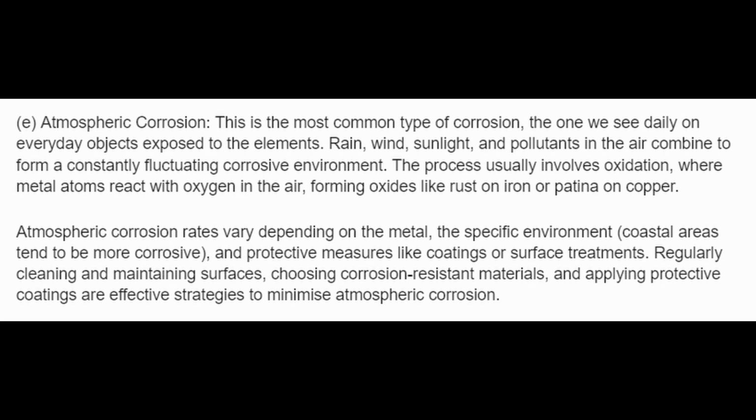The process usually involves oxidation, where metal atoms react with oxygen in the air, forming oxides like rust on iron or patina on copper. Atmospheric corrosion rates vary depending on the metal and the specific environment. For example, coastal areas tend to be more corrosive. Regularly cleaning and maintaining surfaces, choosing corrosion-resistant materials, and applying protective coatings are effective strategies to minimize atmospheric corrosion.